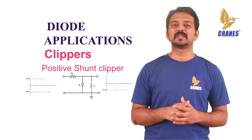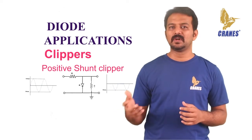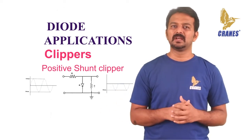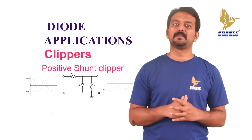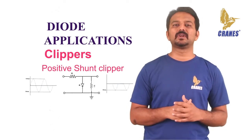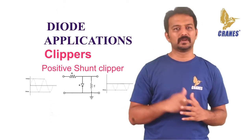Let's look at the positive shunt clipper. The diode is forward biased during the positive half cycle. So the output voltage is 0 as the diode acts as a closed switch. And during the negative half cycle, the diode is reverse biased and acts as an open switch. So the full input voltage appears across the output. With the above two diode clippers, the positive half cycle of the input is clipped at the output.